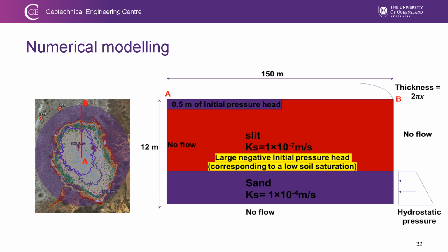Given that there's only 5 meters, and the sealed layer has a relatively steep soil water retention curve, under hydrostatic pressure distribution the surface saturation is about, let's say, more than 50%, but this is not the case. So we basically assume that there is no change of relative permeability as a result of the unsaturated zone.